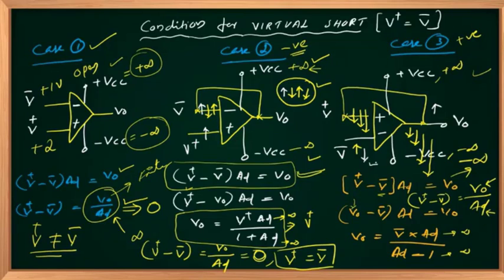That increase is coupled to the positive input, so my output further increases due to an increase in the positive input. That further increase is again coupled to the positive input, and the output further increases. That further increase is available here as a feedback signal. Then my output further increases, and eventually it reaches plus infinity if I am giving plus infinity.